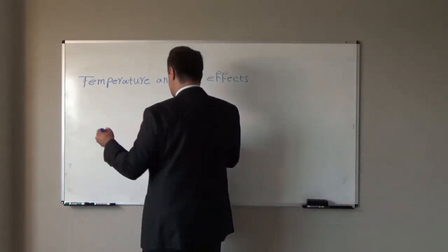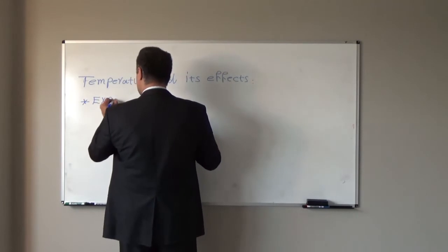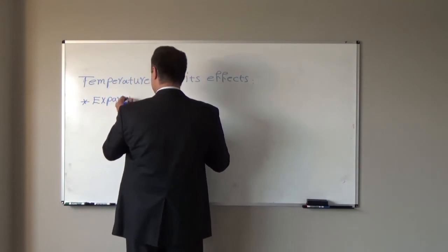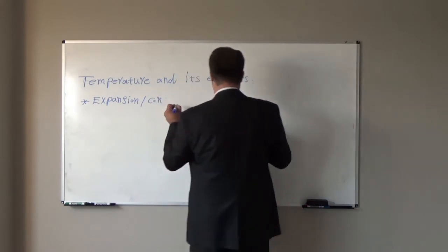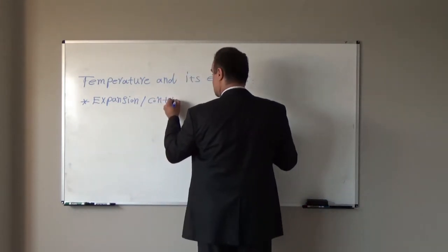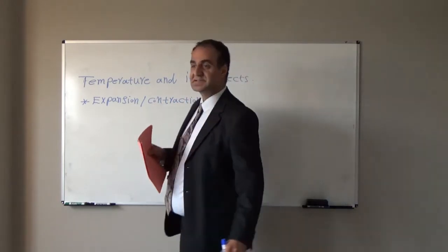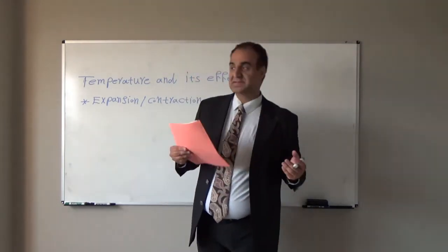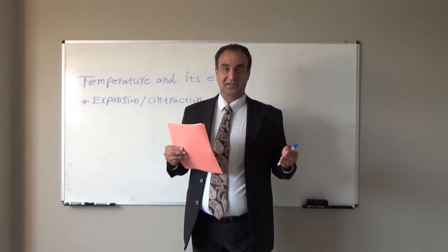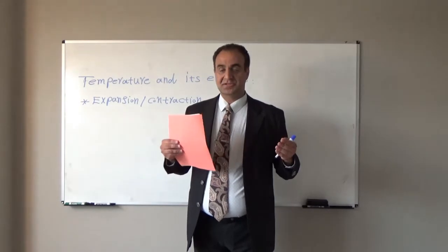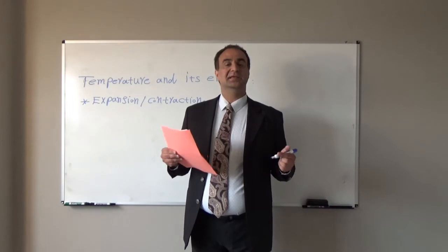So temperature will cause expansion and contraction. If the material is free to deform, it is free to move, this temperature will cause expansion and or contraction, but we will not have any internal stress.